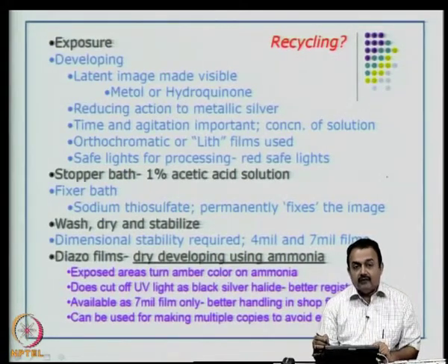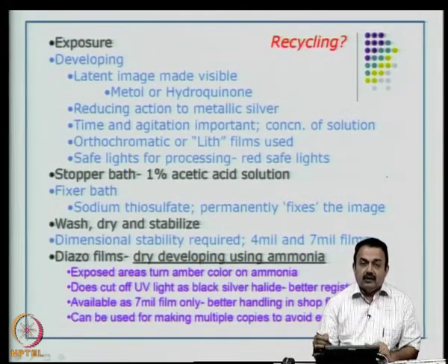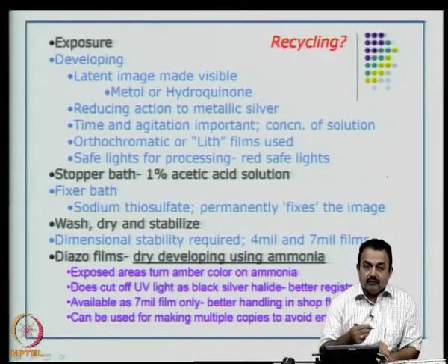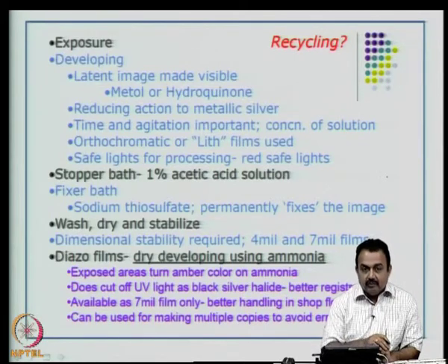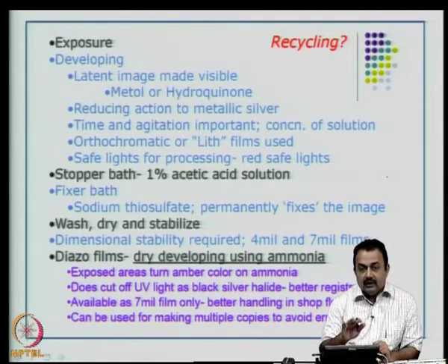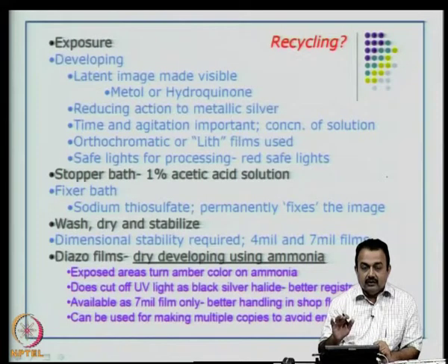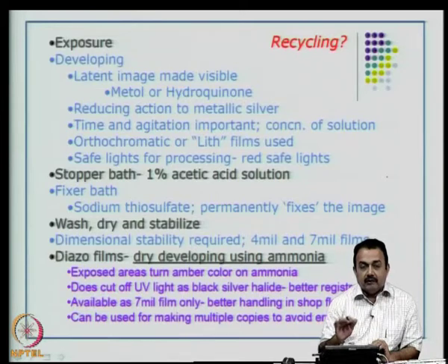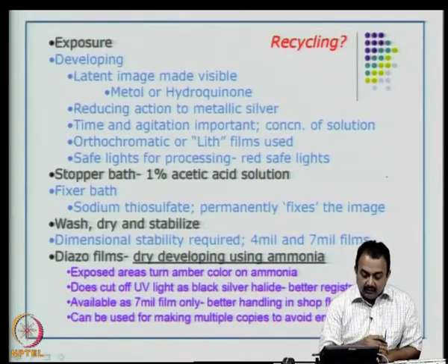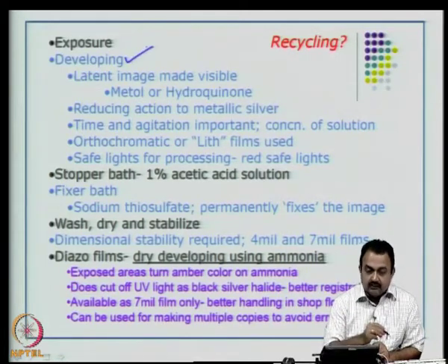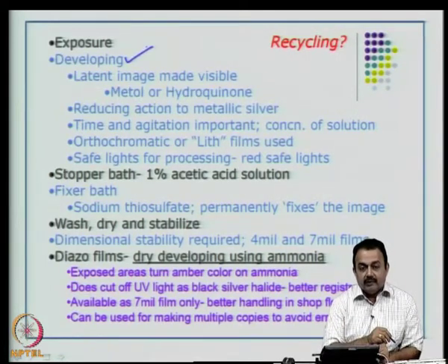So, what is the photographic chemical process that one will actually have to do once the exposure in the photo plotting is done? So, basically the photo plotter does only light source exposure. After that is complete, you can say that the photo plotting process is complete. Then the film is unloaded from the photo plotter and then it goes for a developing process. Now, in the developing process, which is a chemical process, you have a developer solution. What is the developer solution?